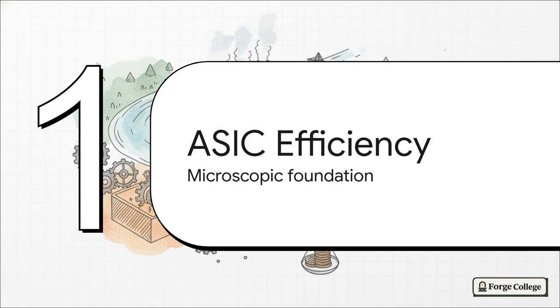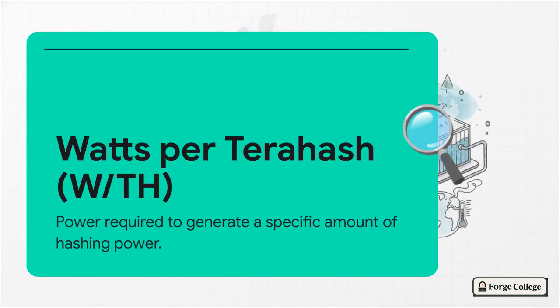All right, moving down to the microscopic foundation of our economics. Layer 1, ASIC efficiency. When we talk about ASIC efficiency, the ultimate canonical metric is watts per terahash, or W/TH. Honestly, just think of it exactly like miles per gallon in your car. A lower watts per terahash number means you've got a highly fuel-efficient vehicle. Dropping from, say, 80 watts per terahash down to 50 is a massive, massive upgrade.